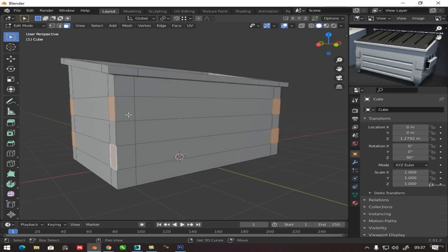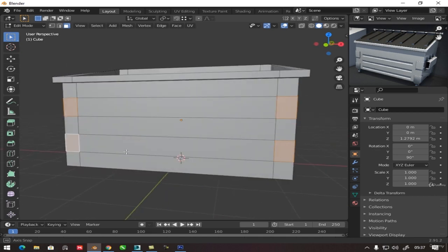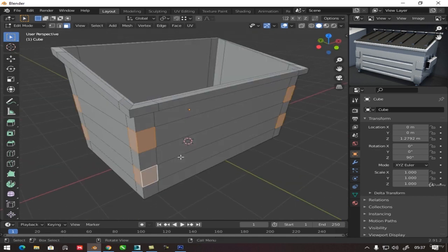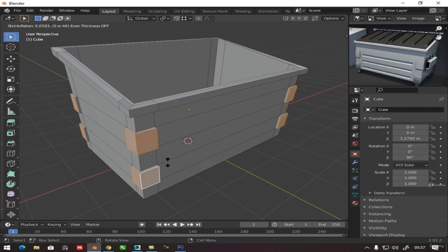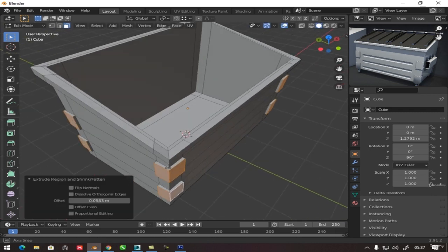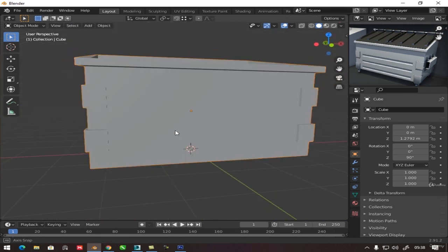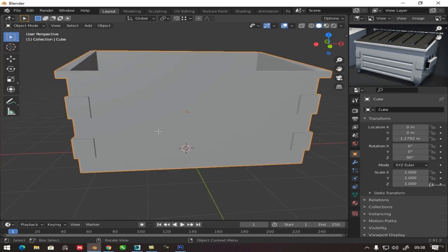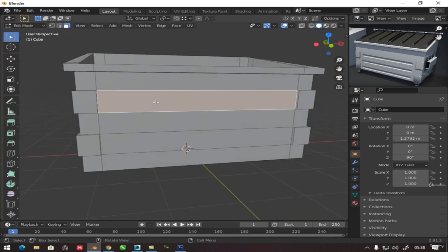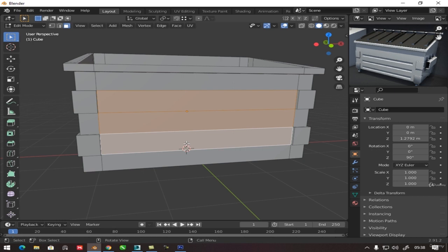So let's go, make things faster here, okay, and then here I can do an Alt E and extrude along normals and bring here, but you can see that some parts are bigger and thinner in some other parts than the other. I could mark the offset even and adjust, and it's good enough to do this way. We already have our result here.